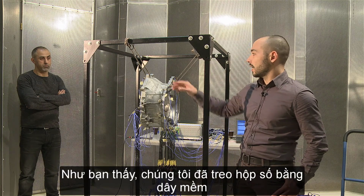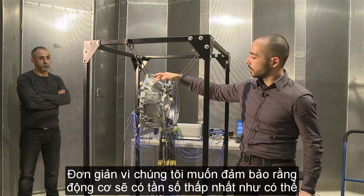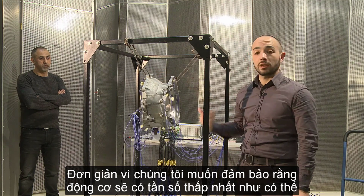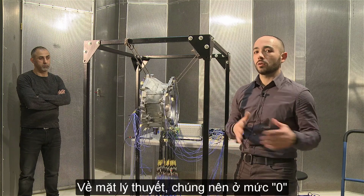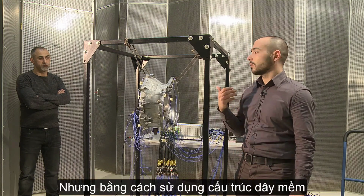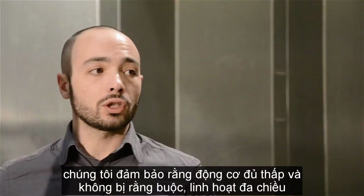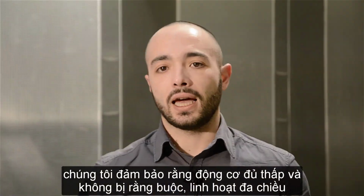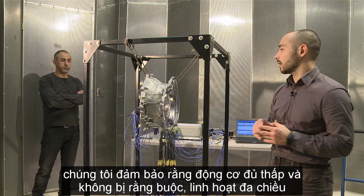Now, as you can see, we suspended the gearbox on elastic bungees, basically because we want to make sure that the rigid body modes will be as low in frequency as possible. Theoretically, they should be at 0 Hz, but by putting the structure on soft bungees, we make sure that those modes are low enough and are far enough in particular from the flexible modes of our structure.